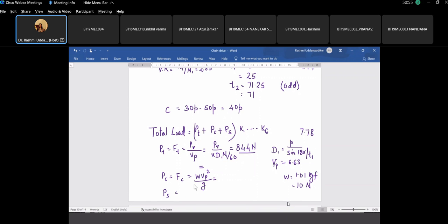So sagging depends upon the coefficient of sag K, in the design data book. Weight is given in the design data book on the same table where you got the breaking load and the bearing area.